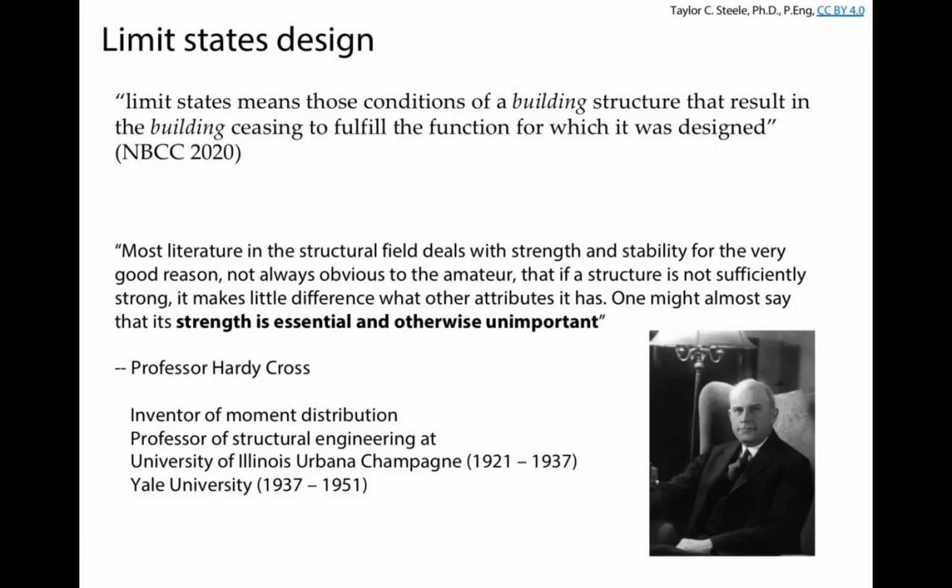It's not the intended function of the walls to crack so that the windows don't open. There are things that the building is intended to do, which means keep people safe. People should be safe in the structures, but we should also be able to use them comfortably. And that's basically going to be the differentiation between ultimate limit states and serviceability limit states.